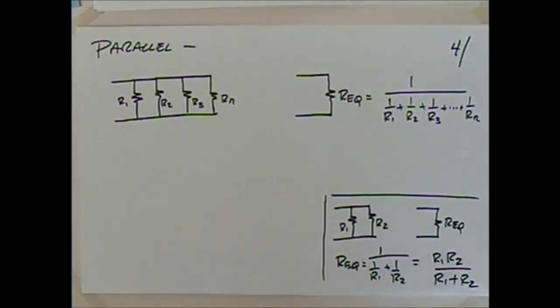So something that comes up when you have two resistors, you sometimes will say product over sum. So maybe you're working in a study group with someone and two resistors, boom, they always have the answer real fast. How'd they do that? That's product over sum. Multiply them together, then divide by the sum of them, product over sum. So it's an interesting case when you have two resistors.